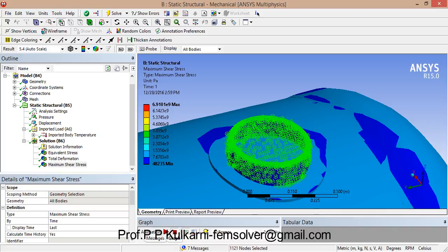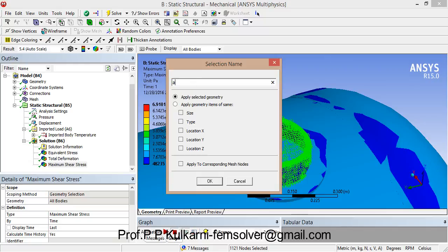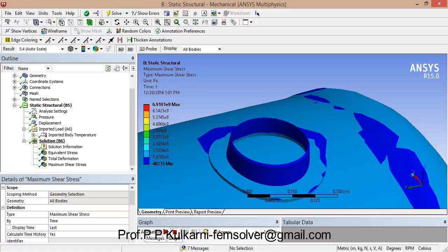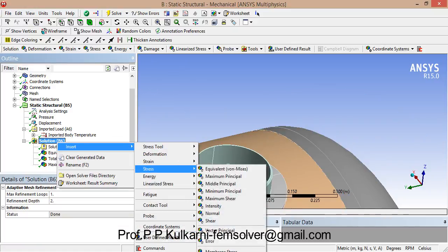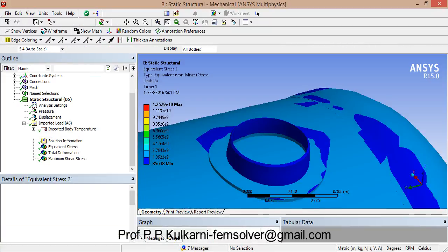This is very important. So localized stresses occur near openings. It may be a nozzle or any opening, or any wall near this, where localized stresses are occurring. So insert, and von Mises stresses are obtained always. Von Mises stress defines the failure criteria.